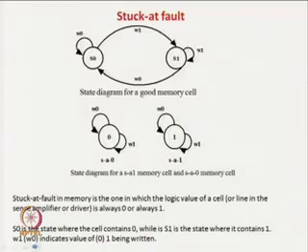The reason behind this is very interesting, because everything is stacked up so near to each other. So, none of the cells can remain very much free, or move freely under the fault case compared to its neighbors. That is why neighborhood pattern sensitive faults or coupling faults have taken a very important role in memory. So, we will slowly elaborate one by one on each of them, and then also see test techniques for them, and we will see why they are more relevant in a memory.